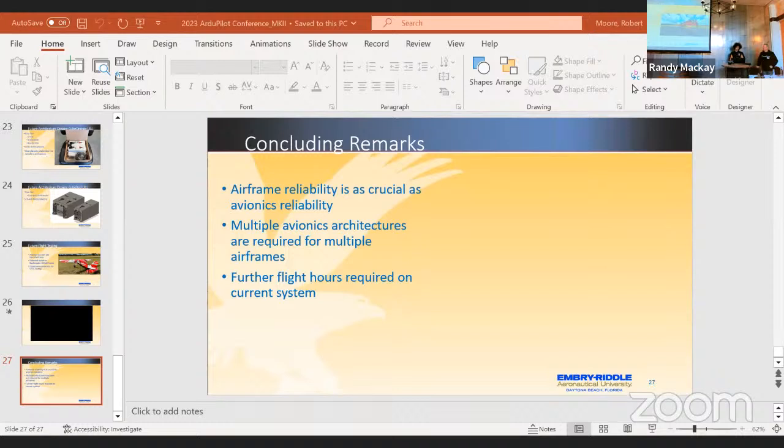Part of the reason I chose this airframe is it's one servo per surface. So if I had a single servo failure, it didn't take down my whole airframe. From the last talk, I gave an example of a single elevator servo on that airframe that burned out and then lost the airframe. So this is a good proxy for a servo per surface. Even if one failed, like I did have one fail, I could still fly it back.